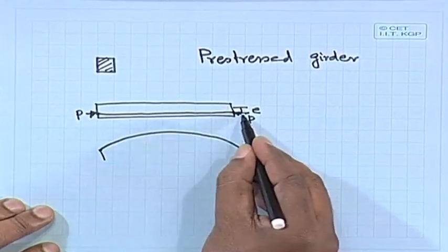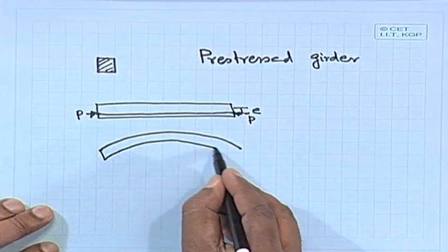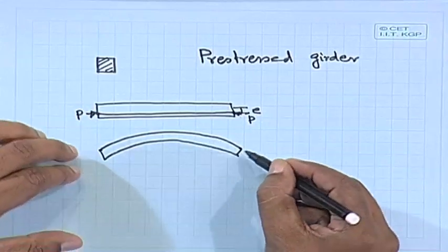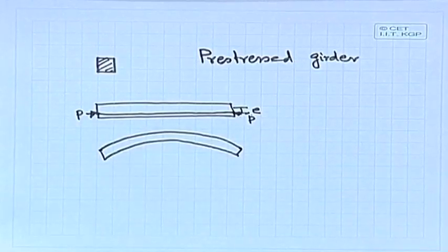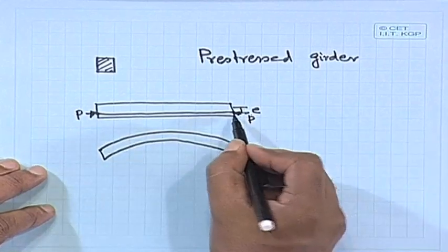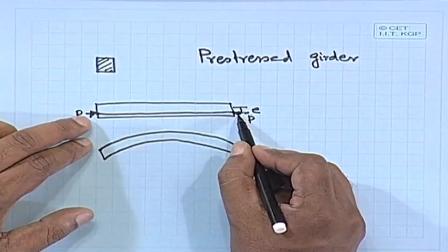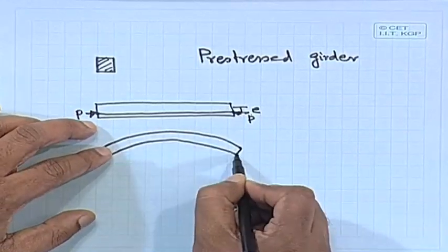Due to bending, due to the moment developed, there is a moment developed here. So initially it will be like this. Not that much, but anyway, it will try to bend in this fashion, because you are applying the load not directly at the center. Instead of that, I am intentionally applying it at a certain eccentricity. So it will develop a moment, and also axial force. So what will happen? It will make like this.